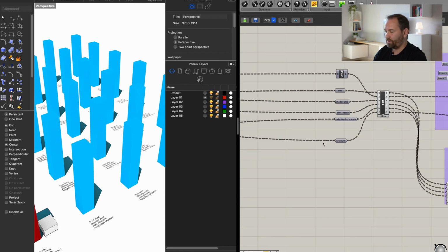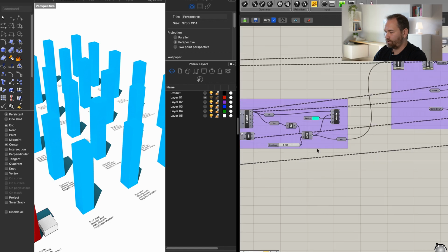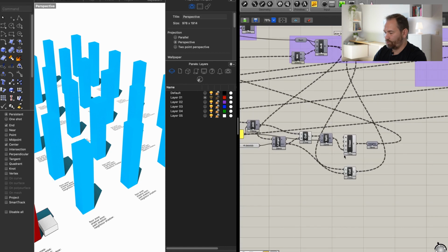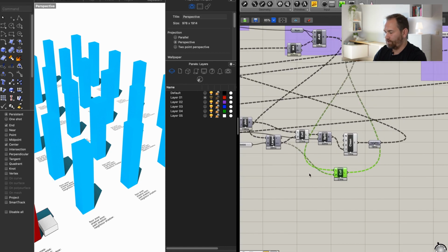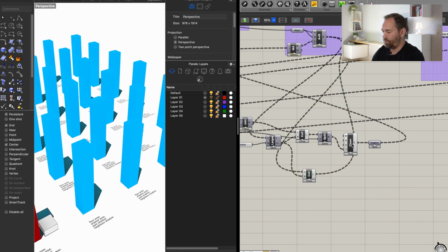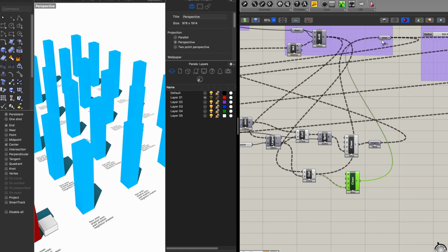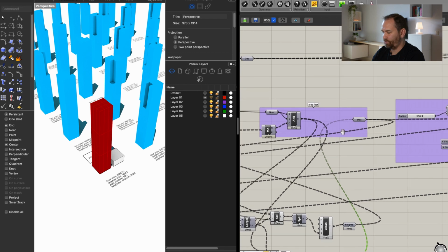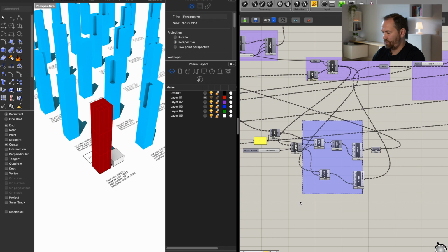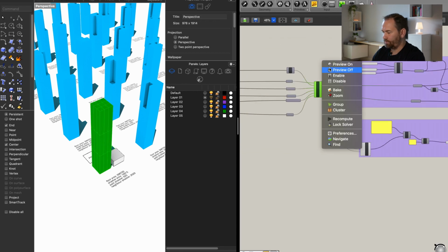So we need to go back. At the beginning of this video we filtered the area, but we forgot to clean the tree. This is happening here. We filtered the area the same way we filtered the heights for the designs, but we forgot to use the clean tree component. Let's just use it now. This is the tree we want to clean, and pass that to the area. As you see, that already fixes the problem. Let's stop the preview of this mesh, which is to be found here and here.